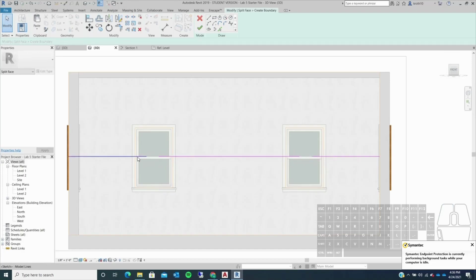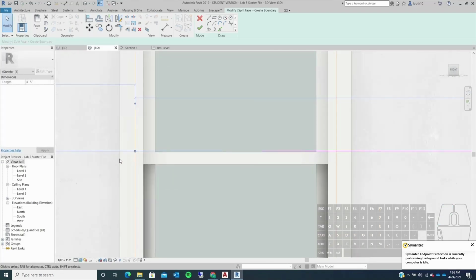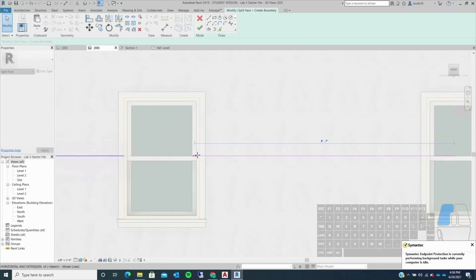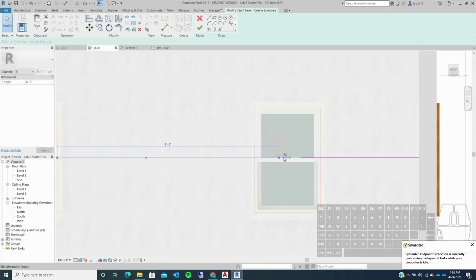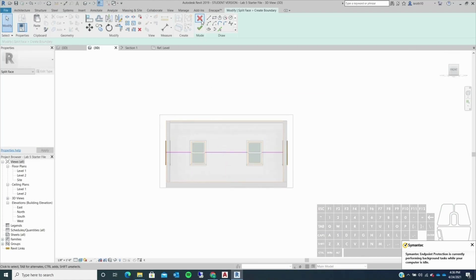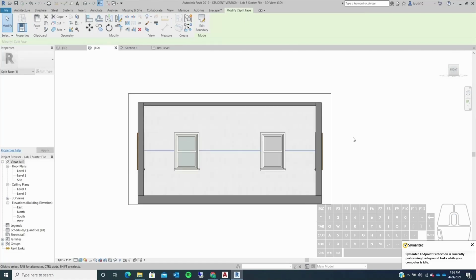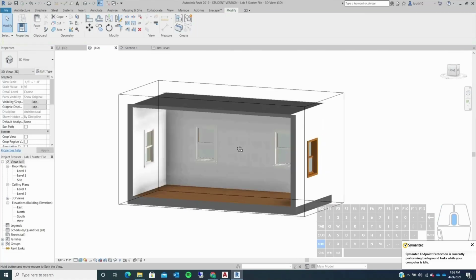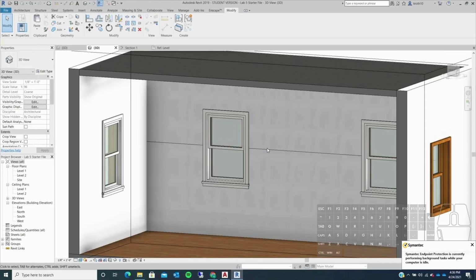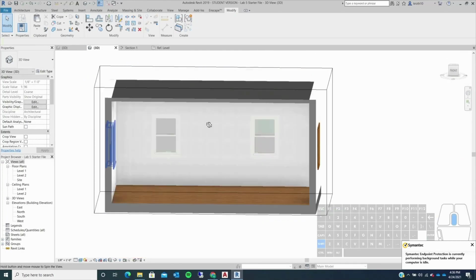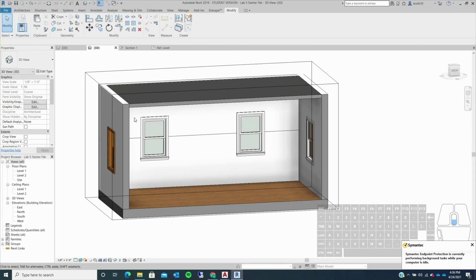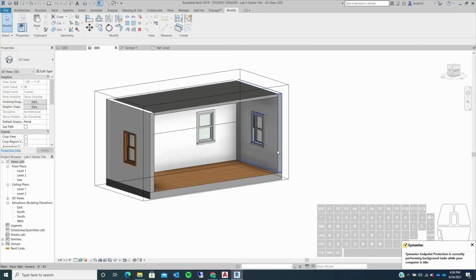After we've done that, we can click on these line segments and manually pull them back until we are perfectly aligned with our orange line on either side. So there, and then here, and one more right here should do it. Then we're just going to click the green check mark, and when we do that, we should get no errors and we should be back in our regular mode, but we should see that the wall now has this black line running through it, okay? And that's going to allow us to apply different materials to the different faces.